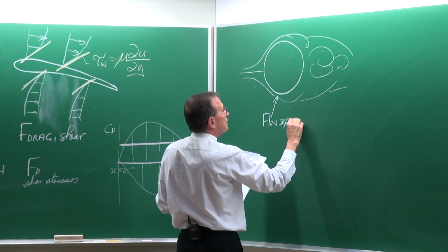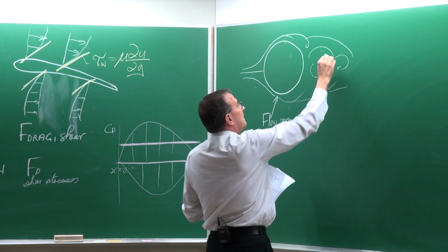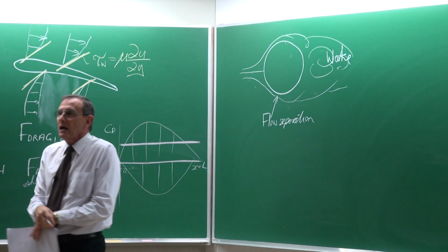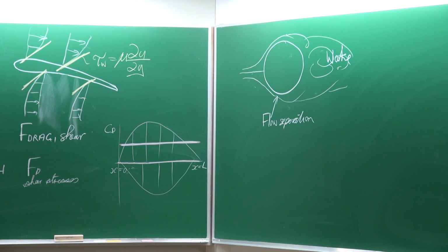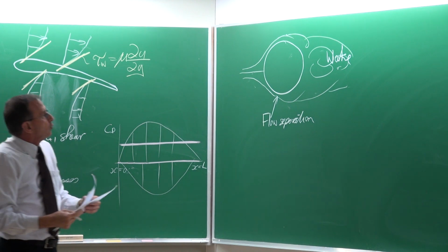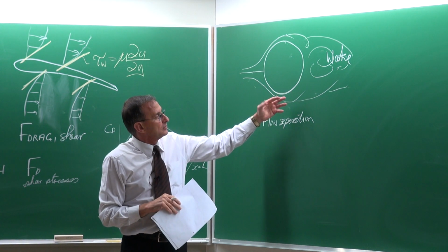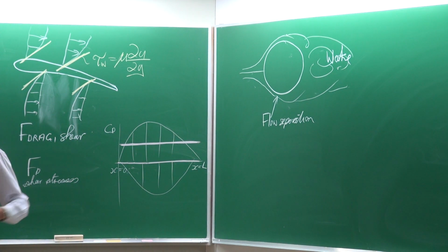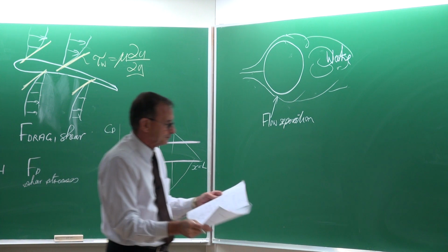This is where flow separation occurs, and this would typically be the wake of the body. Every unique geometry will have a different flow field, and in many cases we would like a wake, while normally in something like aerodynamics you wouldn't like a wake and you do not want the flow to separate.